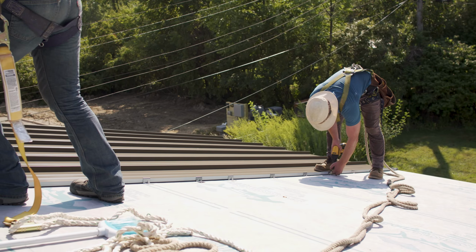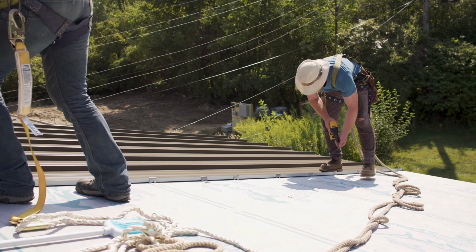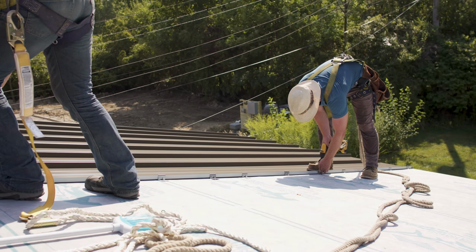If you have higher design pressures that you need to meet, you might have to vary that clip spacing in different zones to meet the higher design pressures in the corners and the perimeters, and then you might go to a further spacing in the field area. It really depends on what criteria the roof's going to require and what the panel met as far as the designs it's able to achieve.